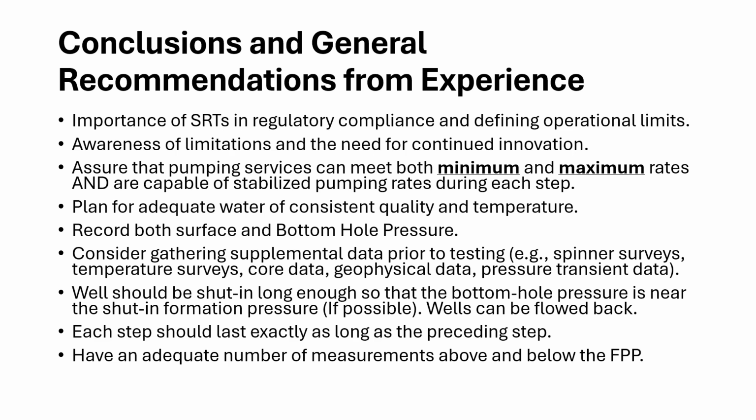So plan for adequate water of consistent quality, consistent temperature, consistent density. That's important for your early time tests. And then we highly recommend that you record both surface and bottom hole pressure, as those can be used in your interpretation. And then we recommend considering gathering supplemental data. These could be spinner surveys, temperature surveys, core data, any of that we discussed earlier.